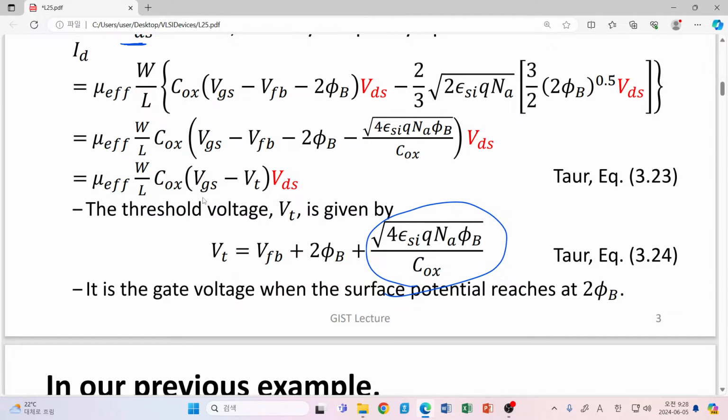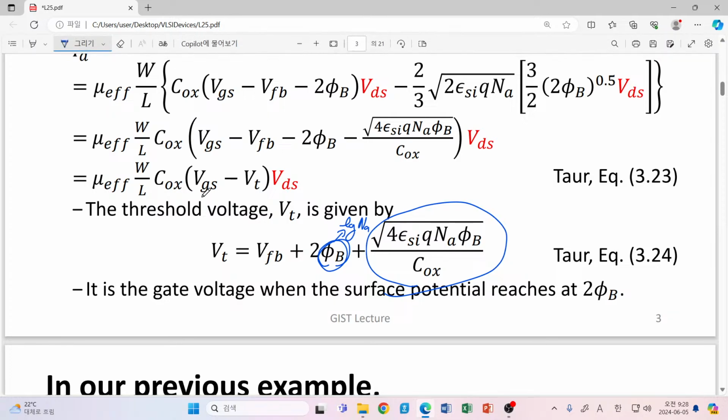So that is the main factor we can consider. Of course, if you increase also threshold doping density, then this is also corresponding to the log of NA value. However, since we just take log of NA value, its increment is not that drastic, so it is not a main factor. Well, so anyhow, if we increase the dopant density NA, then we can increase our threshold voltage.